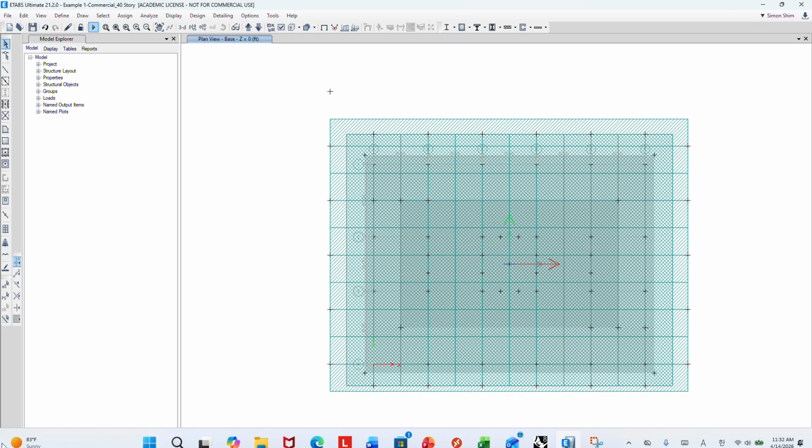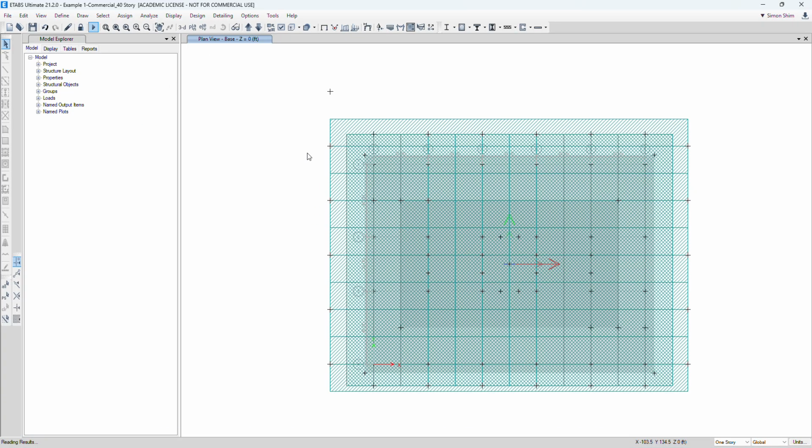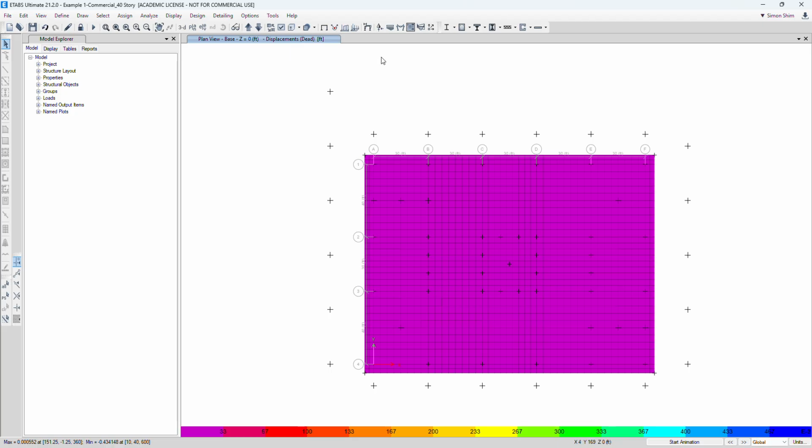But a beam is mostly one direction, and a mat is two direction, X and Y. So when I cut this, it means all the forces spanning in this direction. If I cut this section, they are collecting the forces in the Y direction. You can show the design forces, which are shear, moment, and axial force, right?